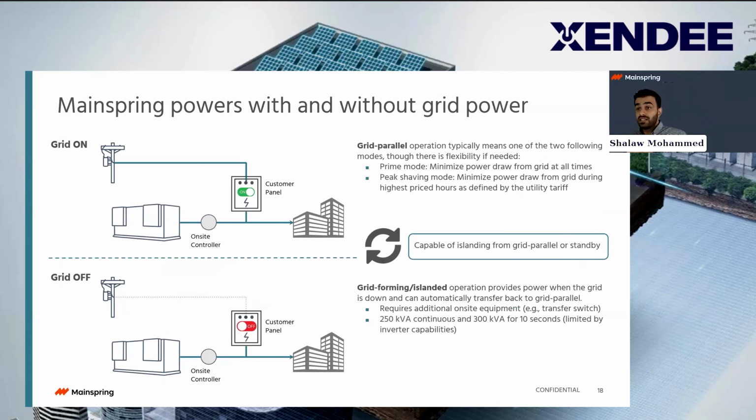All right, so because of the controls on the system, we have a lot of capability to perform in different modes. Obviously, that has enabled us to operate in 2 modes: grid parallel mode and grid forming mode. When we're connected to the utility, we can sync into the utility voltage and frequency and supply the system. And because this is an inverter-based technology, the inverter actually does that.